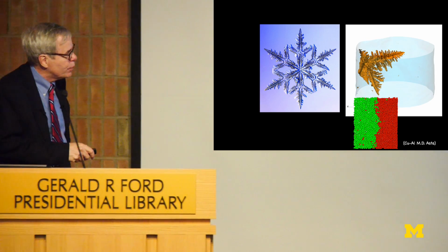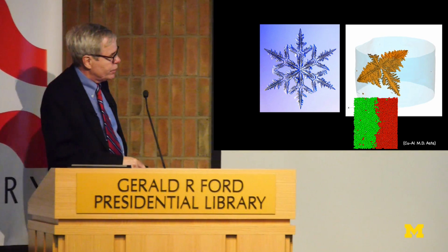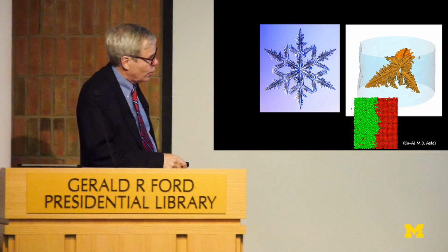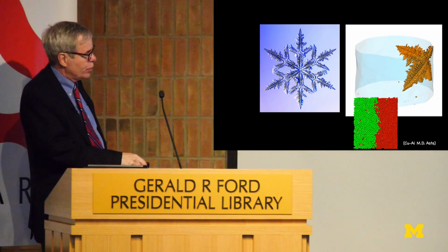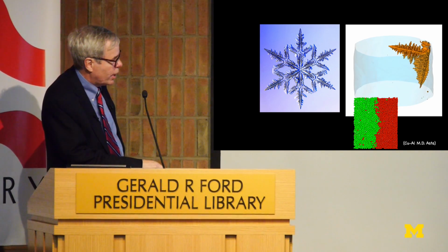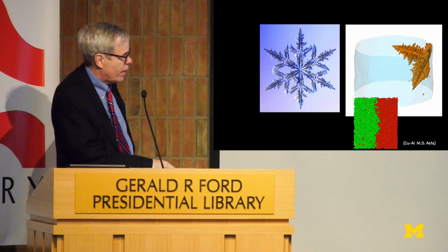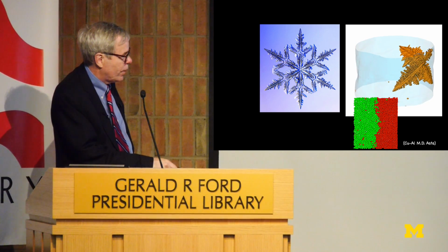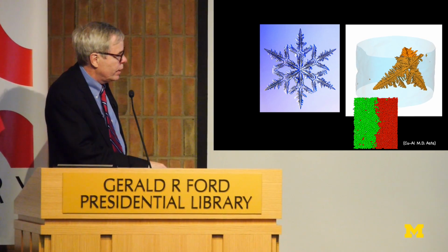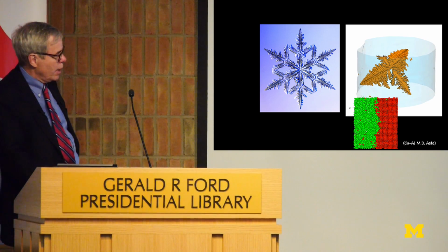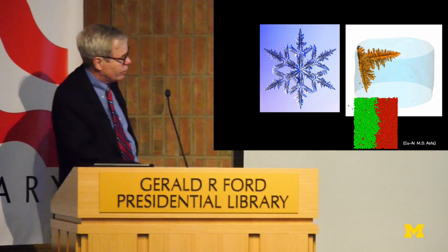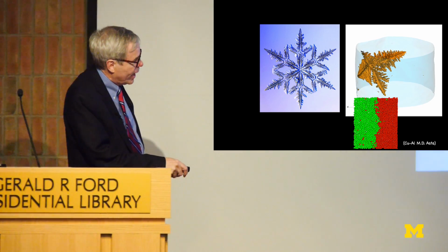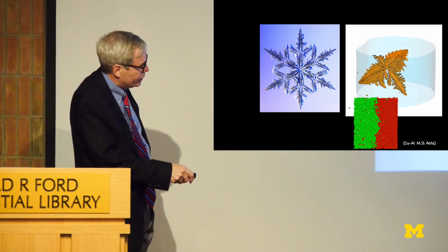If you look at the solid-liquid interface here, these are the atoms along a solid-liquid interface. This is a molecular dynamics simulation. So this is the crystal over here, and you can see that they're all lying in a very crystallographic nature. They're all lined up in great order. The liquid is highly disordered. And this interface here is what is called atomically rough. It's very easy for an atom in the liquid to join the solid because it's atomically rough.